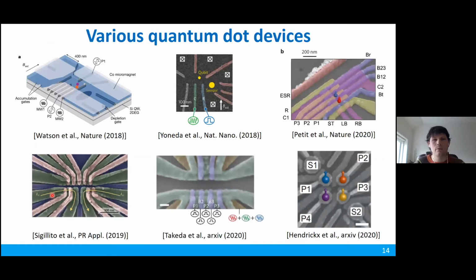So what do typical quantum dot devices, and the most recent devices, look like? There are all kinds of different materials being used, and also different gate layouts. But they all have one main thing in common, and that is how the charge sensor is positioned. These charge sensors, here indicated with this blue ellipse, are placed close to the qubit. And here, indicated with this yellow circle, there's a charge sensor also close to the qubit. The charge sensor here would be defined underneath this gate, again close to the qubits.